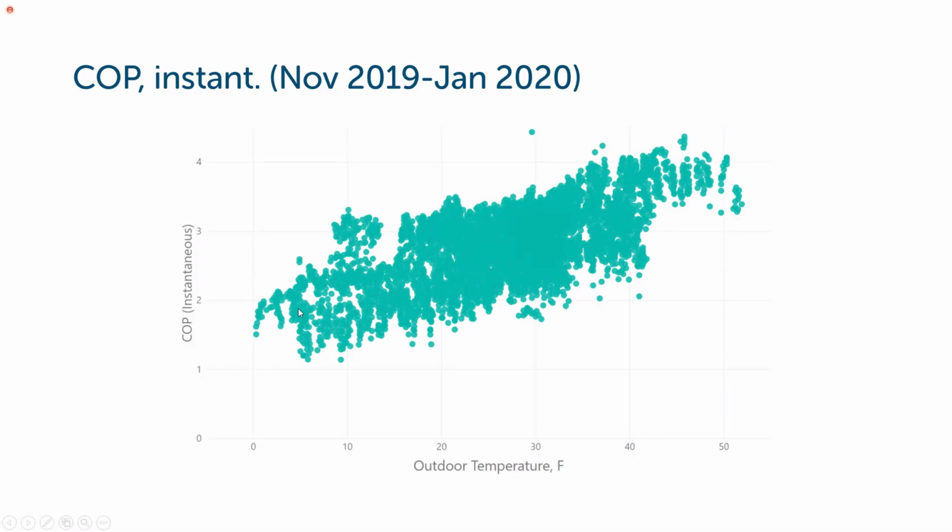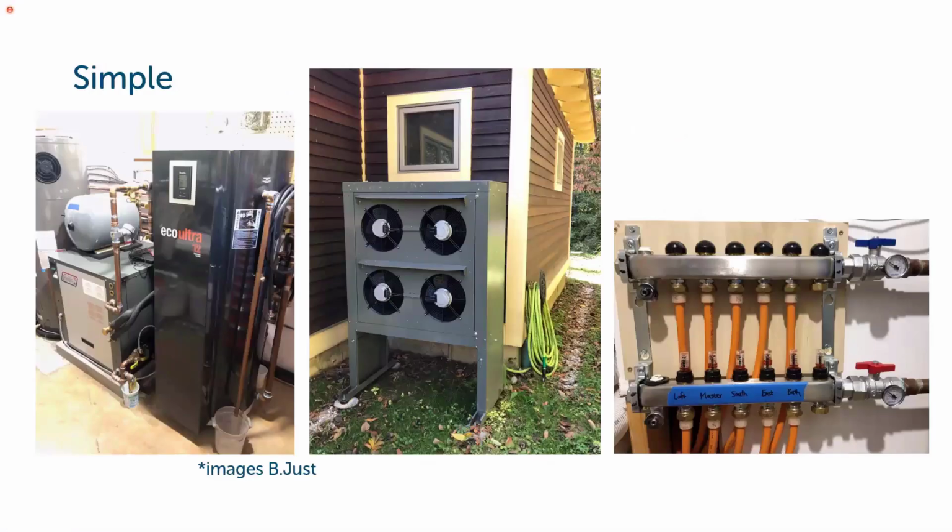In the overall system design for air-to-water equipment, as you get below 0 degrees, the performance of the heat pump starts to be impacted. You have in the buffer tank a 20,000 BTU electric resistance element that is there to help maintain temperature in the tank when the outdoor heat pump unit is still able to meet temperature, but it may not be doing it as efficiently.